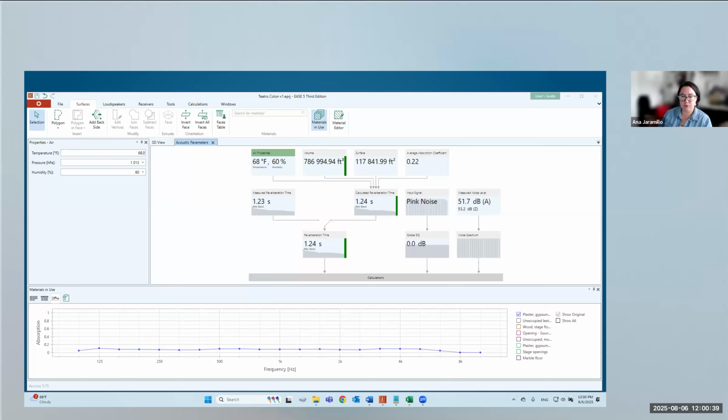For example, for absorption, we know that if we use kind of a checker pattern of absorbers on the walls, the edge diffraction is going to add absorption that EASE is not aware of. So we can make some assumptions regarding those things if we know the details. But I wouldn't say that we can assume it's always going to be higher.